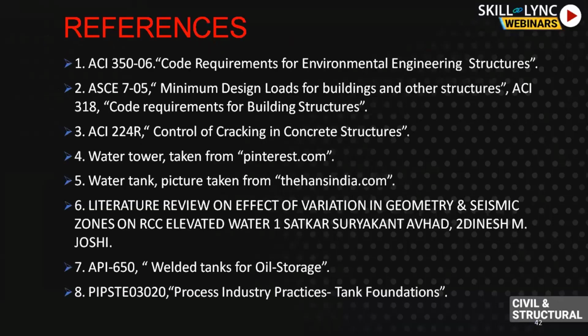These are the references, as I mentioned, most of them earlier. Code Requirements for Environmental Engineering Concrete Structures, ACI 350-06. Minimum Design Loads for Buildings and Other Structures, ASCE 7-05. The minimum crack width requirements as per Control of Cracking in Concrete Structures, ACI 224R. And wherever I have taken pictures from somewhere, I have listed them down. The most important for fuel tanks: API 650, Welded Tanks for Oil Storage, and Process Industry Practices, Structural Engineering PIP STE03020, process industry practices for tank foundations.